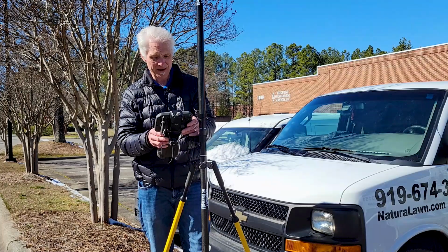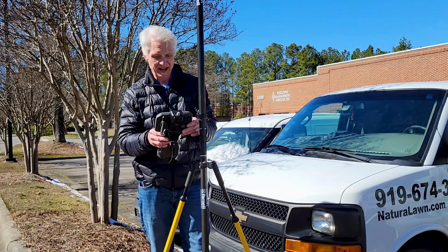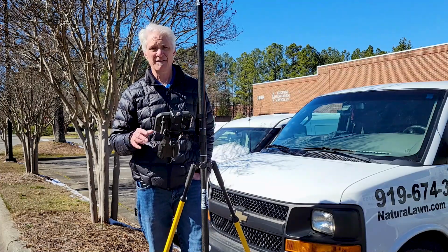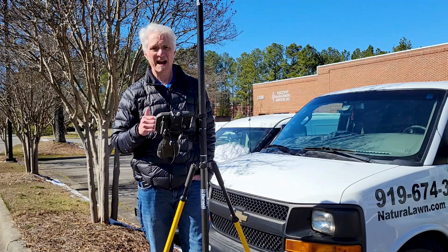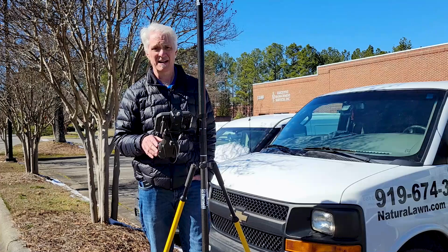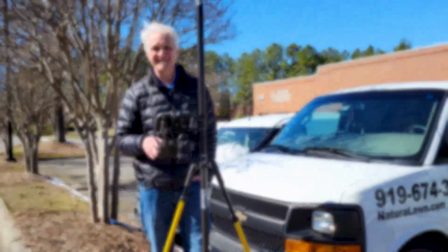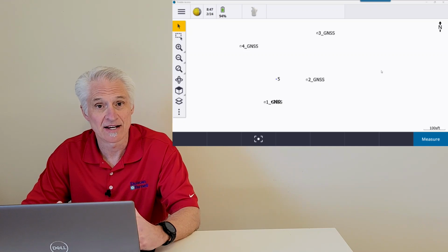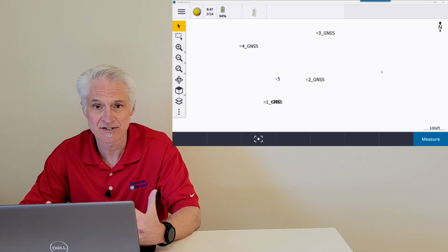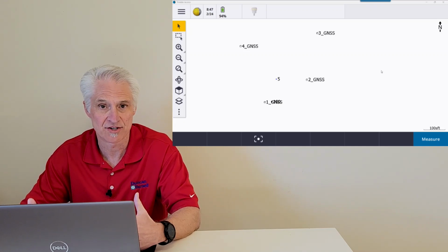So I'm going to escape out of my stakeout screen, escape again, and we'll head back in the office and we'll take a look at the results here and explain to you guys a few things that are going on in the site calibration. See you back in the office. We're back in the office, and I just wanted to open up Trimble Access and take a look at the site calibration and just cover a few things that you want to check.